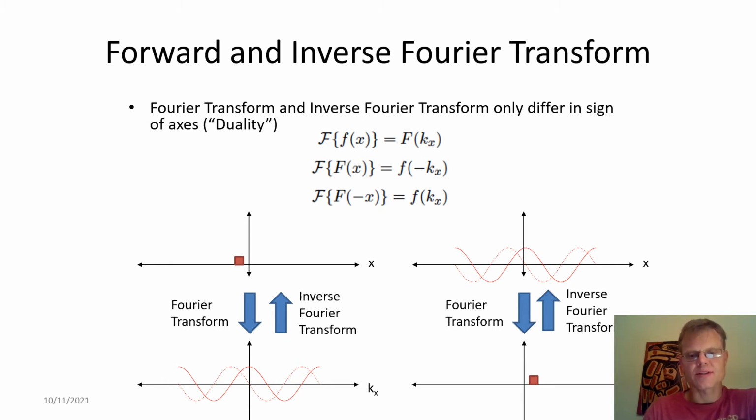We take that complex exponential sinusoid and then take the forward Fourier transform of that, and we flip our delta function across to the other side. So we just get this sort of flipping effect if, for example, you mix up the forward or the inverse Fourier transform.